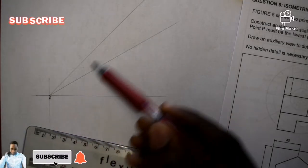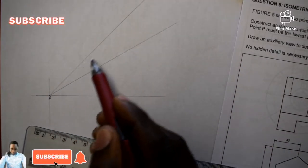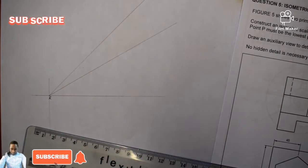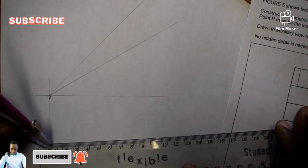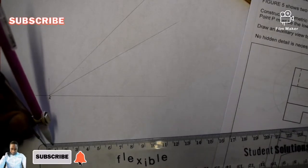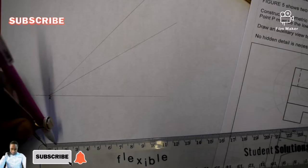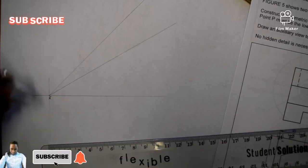Along the line of 45 degrees, I am going to mark 10mm intervals up until 100. It's simpler and faster when I'm using a divider or a drawing compass. So this is my 10mm.